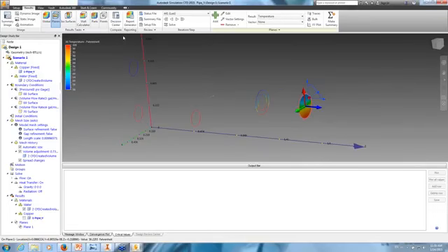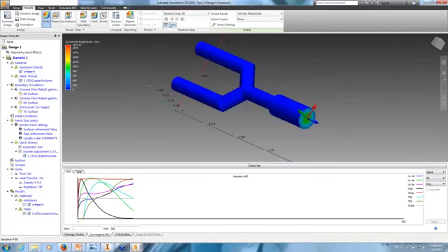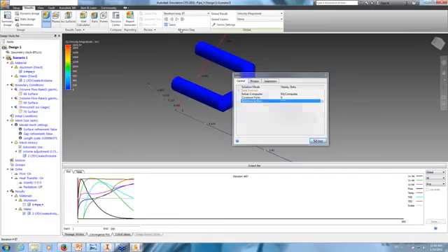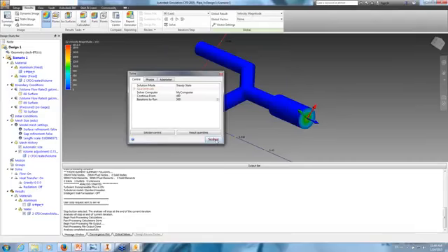So in this example, we did both fluid flow and thermal calculations. I'm going to go ahead and stop this analysis here by clicking on solve, which will bring up my solve dialog. So anytime you want to stop the analysis, you can do that and click on stop. Now, depending on how complicated the calculations are, it might take a few seconds to stop or might take a bit longer to stop. So I went up to the 90th iteration here before I stopped it.